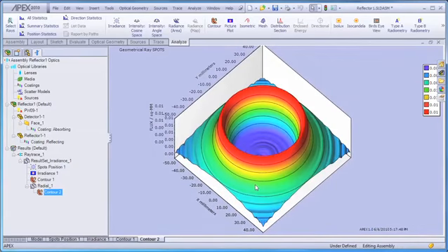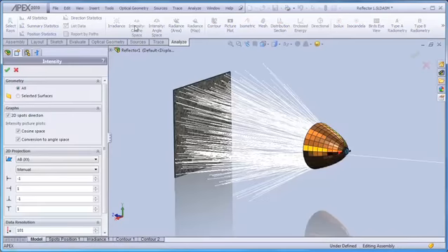Now that we've viewed the irradiance distribution on our detector surface, we can immediately calculate the far-field intensity, in this case for all rays in the system, including rays at the detector as well as rays coming from the faceted reflector, which missed the detector surface. We'll again create a 2D spots diagram, in this case in direction cosine space, showing the angular distribution of our ray set, and we'll plot an intensity map in cosine space as well as in angle space.